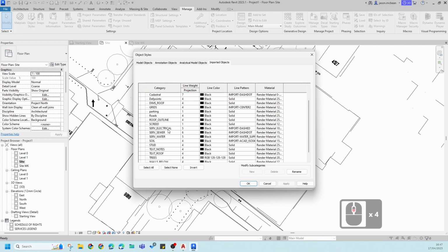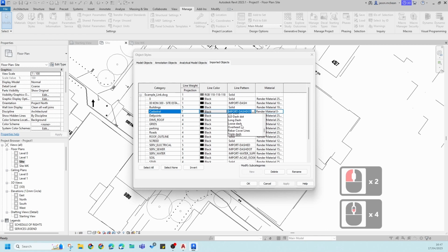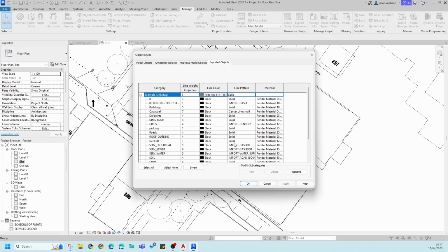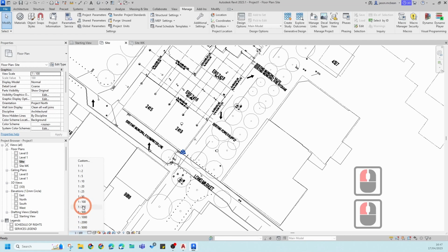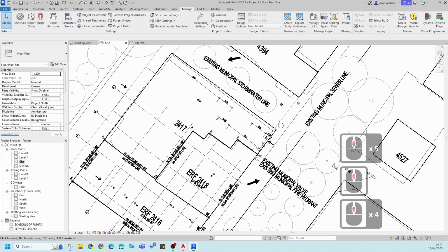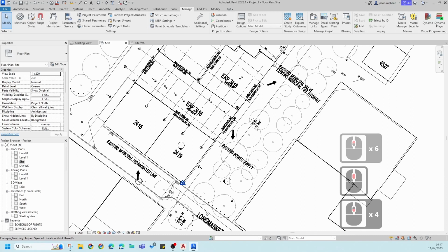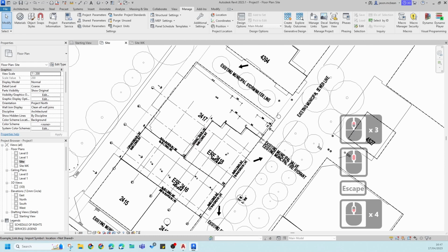So here if you go to building, let's go cadastral. Here I'm going to make this a better dash line because that might not be, so I'm going to say center line small for the time being, and it's on the correct layer, press apply, and you can see you can fix this stuff very quickly. And remember, site plan, here you can change that 1 to 200 and it'll automatically scale up the cadastral information. So you can see a couple of clicks, this is really starting to look way better, and it brings the text in quite nicely, so you can keep a lot of that information. Provided you're using the same font styles in Revit, you can make it look pretty neat.